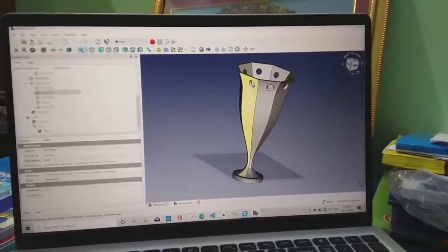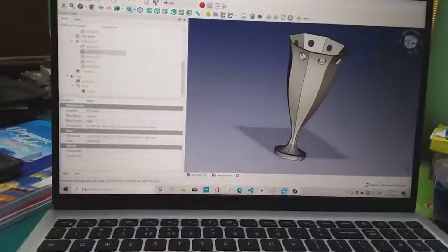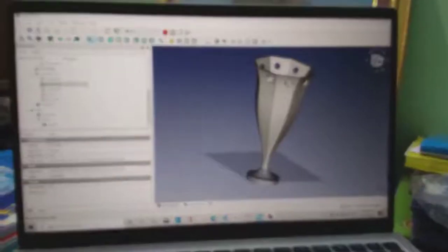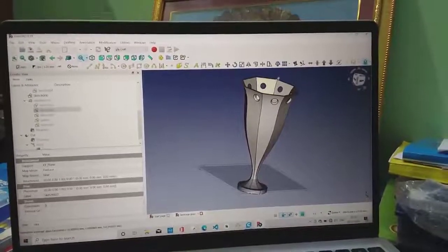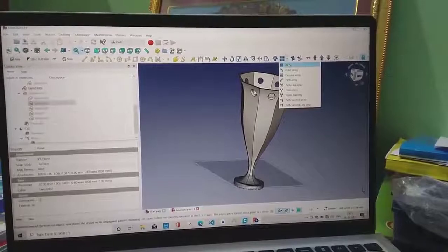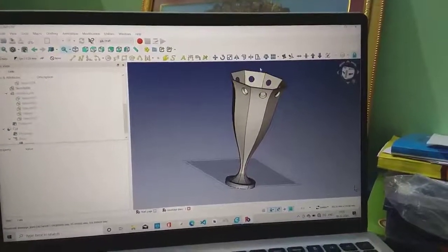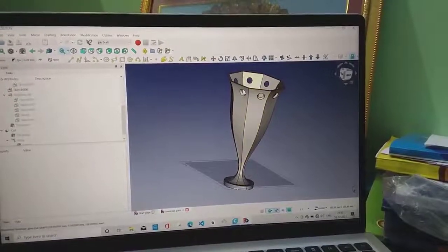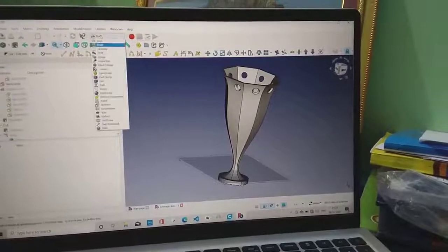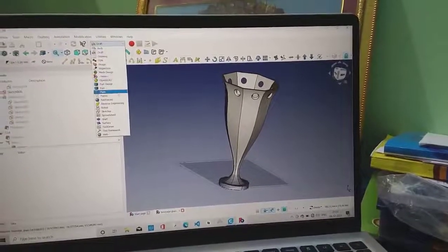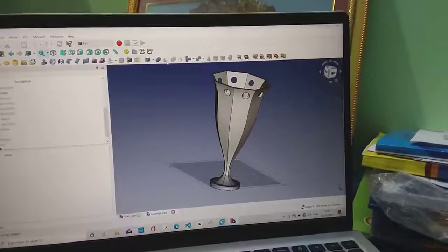Before creating the cut option in the Boolean feature, I have also used the polar array. As we can see here, we can create a polar array. This option we can create in the draft. In the draft option we can use this. Here the polar array options are there. So I have placed the center of the polar array at the 0, 0 axis, and the number of arrays is of course 8, and then I have used the Boolean feature, this option I have used.